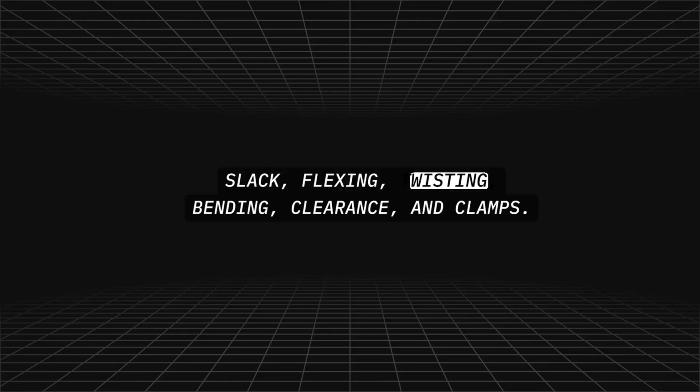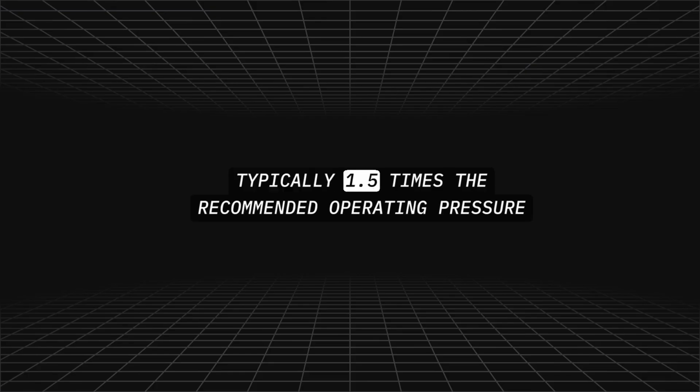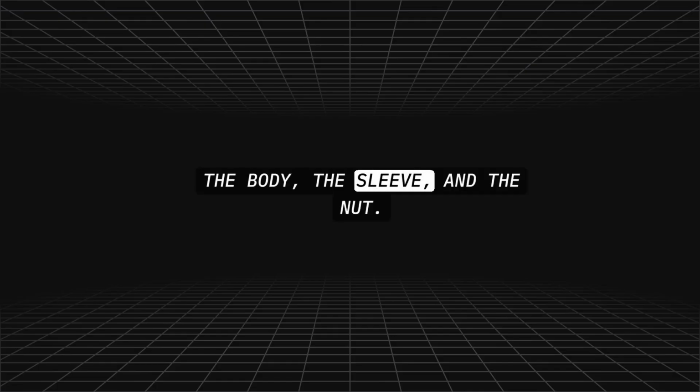Slack, flexing, twisting, bending, clearance, and clamps. What pressure is used to proof test a flexible hose assembly? Typically 1.5 times the recommended operating pressure of the hose. What are 3 parts of military standard tube fitting? The body, the sleeve, and the nut.